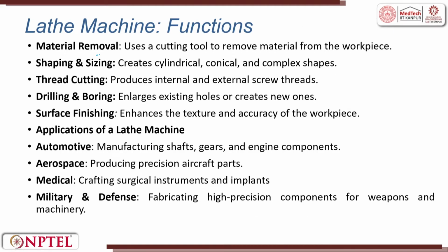So, some of the functions: material removal, using a cutting tool to remove the material from the workpiece. Shaping and sizing, creating cylindrical, conical and complex shapes. It can create shape and size. Thread cutting is also possible. Thread cutting we will see in more detail when we see when we engage the feed rod and the lead screw. Right. So, it produces both internal and external screw threads. Drilling and boring is possible. Super finishing enhances the texture and accuracy of the workpiece.